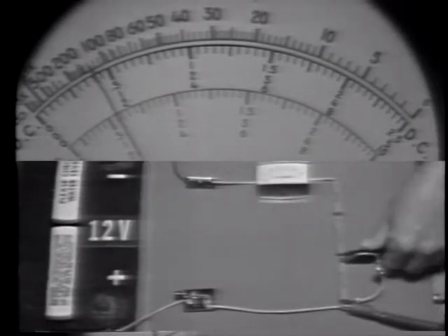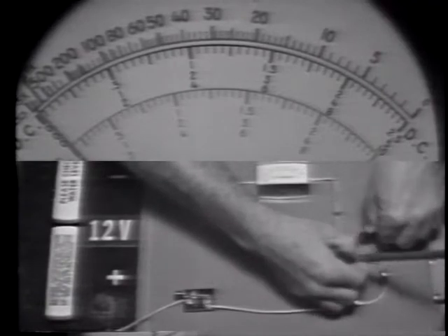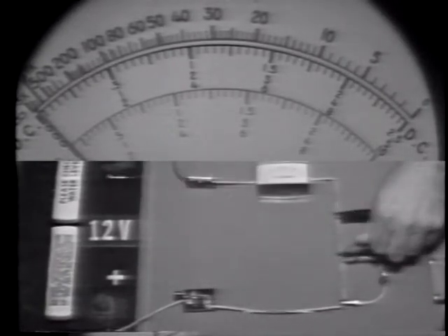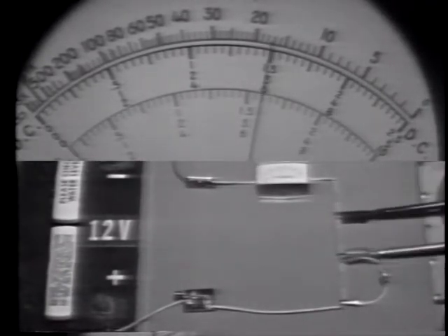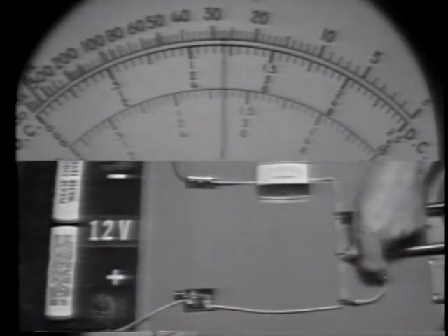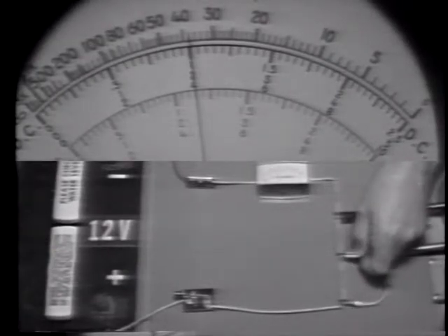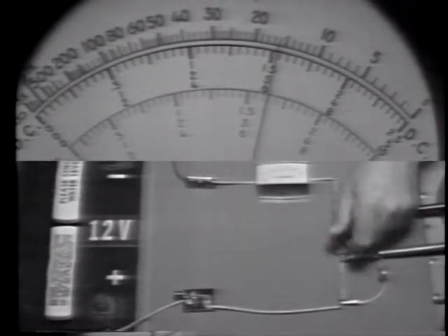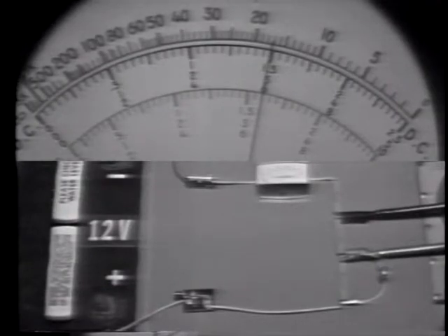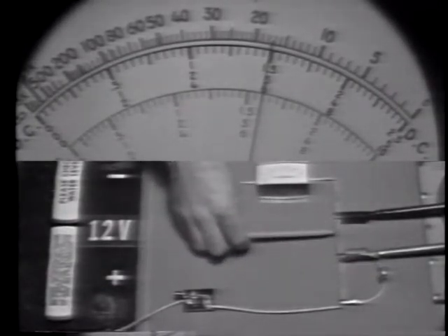Well, let's move up to the other resistors. Let's do the same thing as we check the voltage across this one. Okay, with the load device connected, the voltage there is about, well, let's call it 6 volts. Now watch what happens as I remove the load. The voltage decreases to 4 volts. When I add the load device, it increases to 6 volts. So when we load the circuit, the voltage here increases.